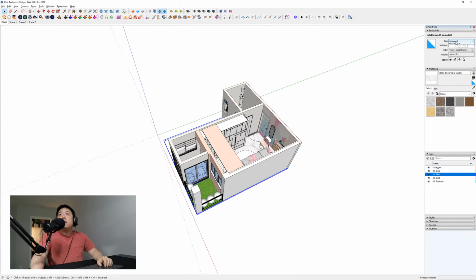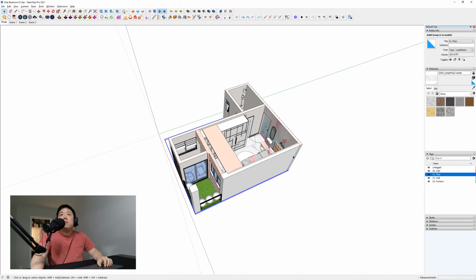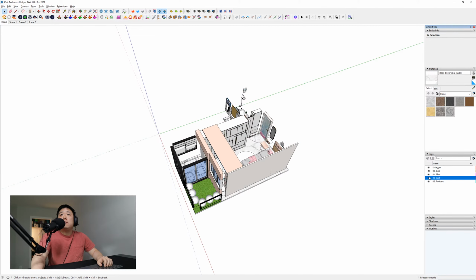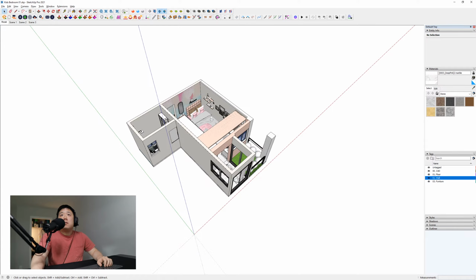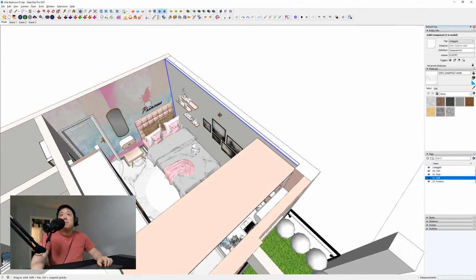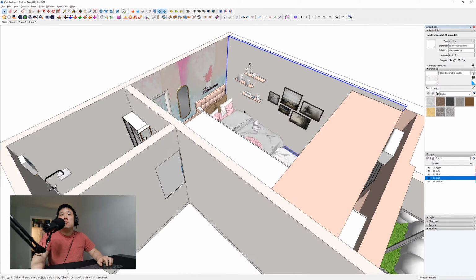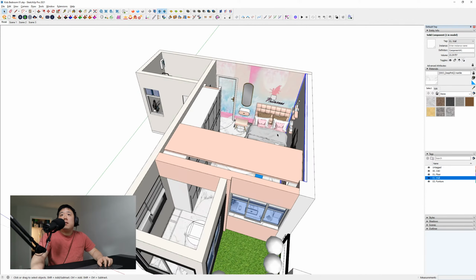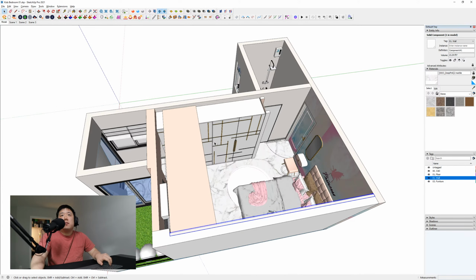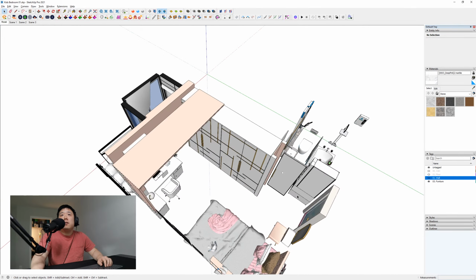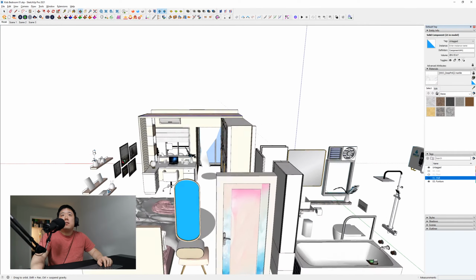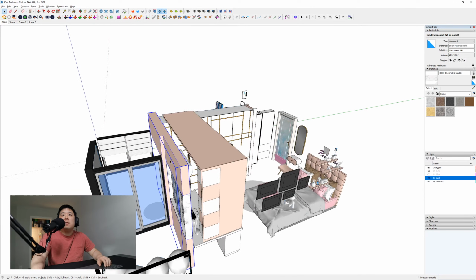Yeah, and then designate that as a floor, so we can turn the floor on and off, and the walls on and off. This is an interior fur out of a wall. I would still put that into the wall. And then the rest of it could kind of go to the furniture. So if I keep all of these layers off, and then perhaps designate some of these as a wall, or I can maybe put this one as a wall as well.